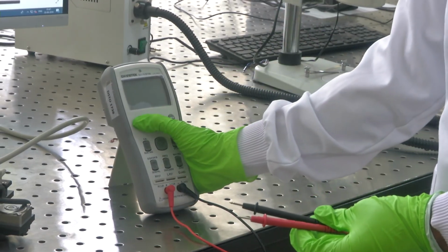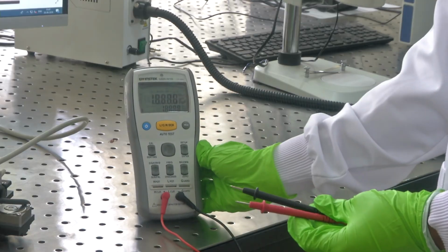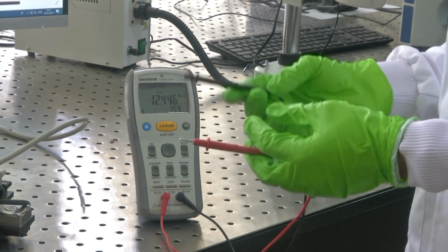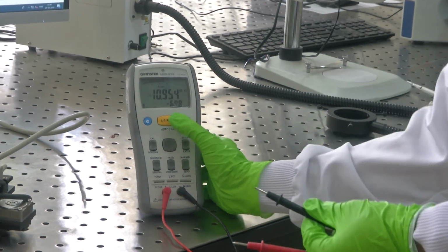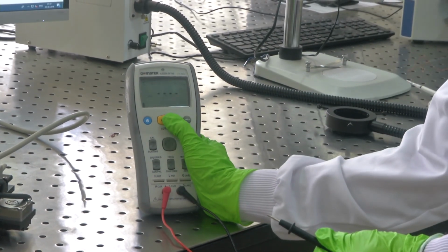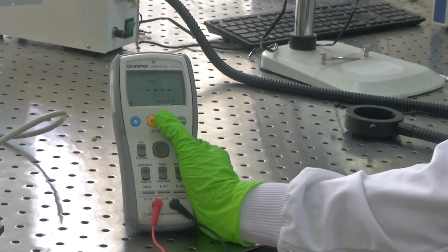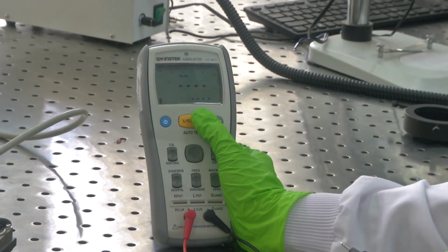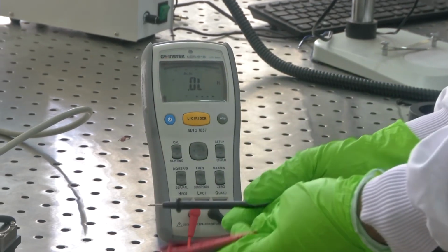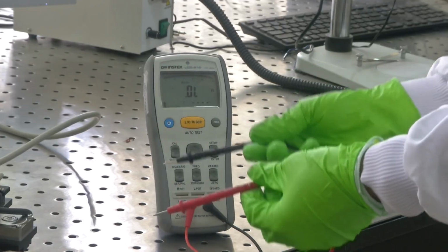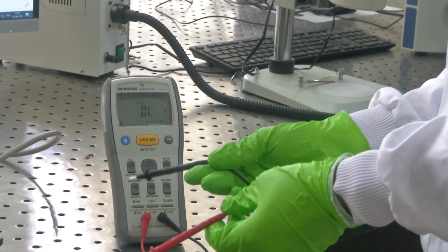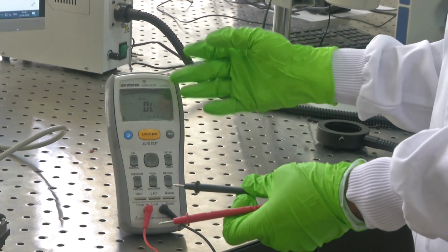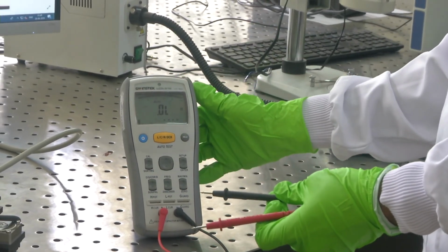I am pressing the power switch button. You can see the display turning on. Using this probe, you can actually do the measurements. You can change between the different modes such as L, DCR, C, R, etc. Now, if we connect these probes across the measurement or the DUT, we will be able to measure the data and see this in real time on the device. This is how we use an LCR meter.